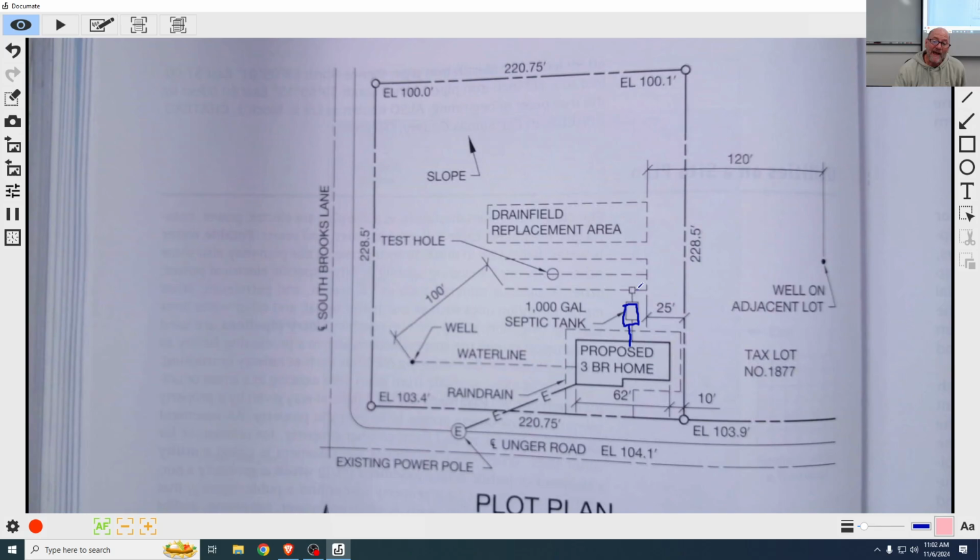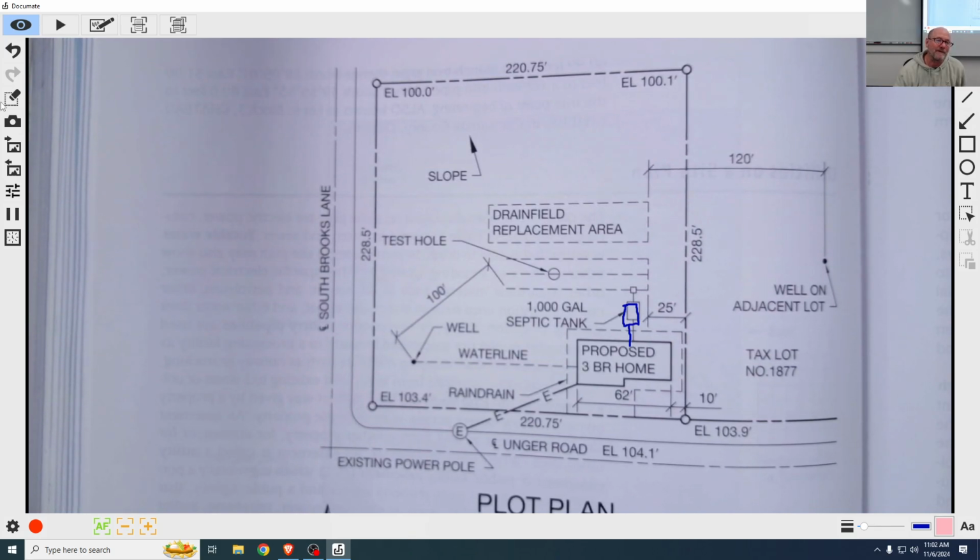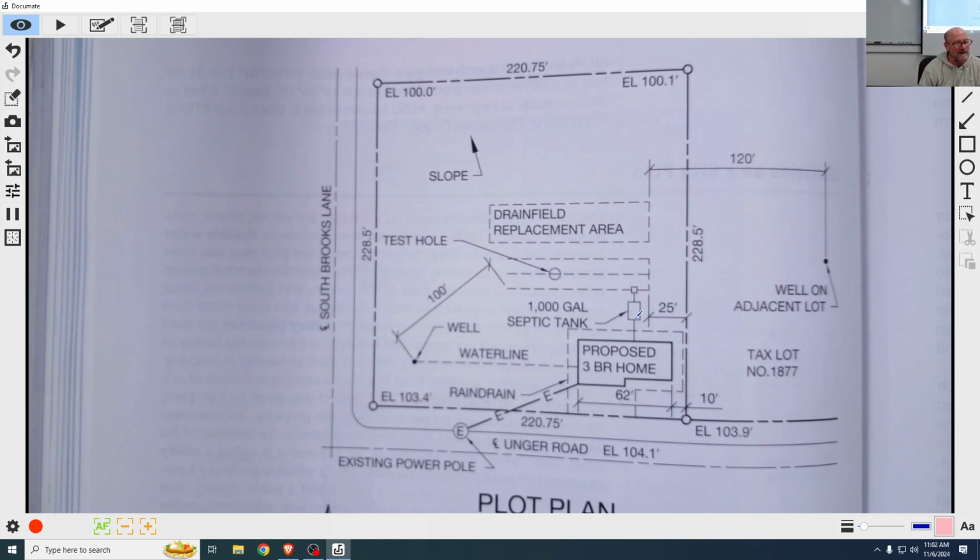And then there's a pipe going out that's in between, so it's below the top, so that the floaties don't go out of it, but the regular water does, right? So as the septic tank allows the heavier materials, sludge, to settle at the bottom, enzymes will eat that away, so it won't just keep filling up, right? In a healthy system, it's this little ecosystem of grossness that allows enzymes to feed away at the sludge and the floaties.